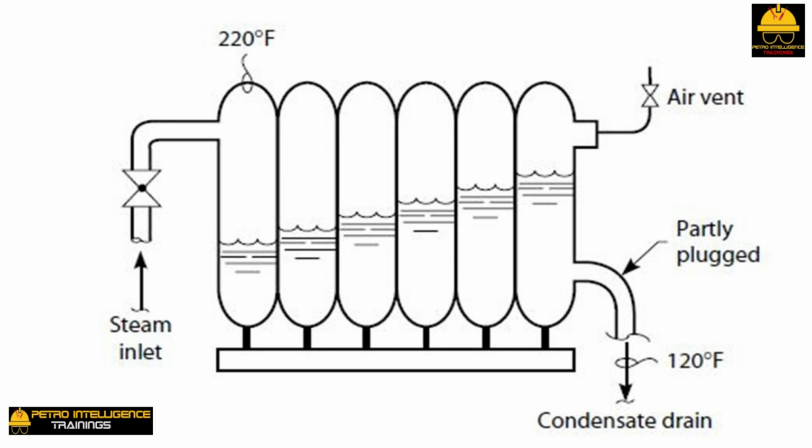To summarize, the effect of restricting the condensate flow from a radiator or condenser is to build the water level in the radiator, reduce the rate of latent heat transfer from the steam, increase the rate of sensible heat transfer from the condensate, and reduce the overall heat transfer duty from the radiator. Incidentally, the correct way to remove hardness deposit is by chemical cleaning. Violent banging on radiators is considered bad form in colder areas.